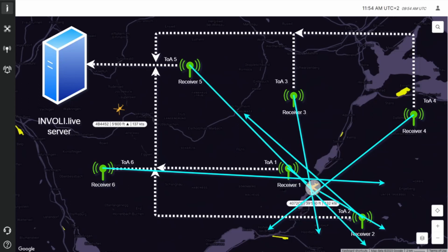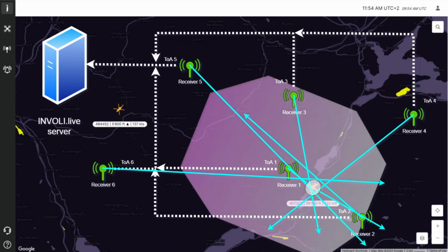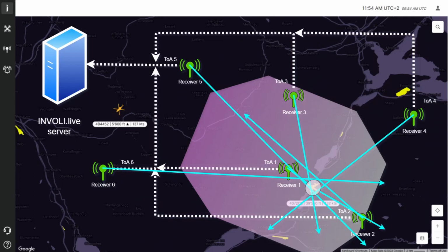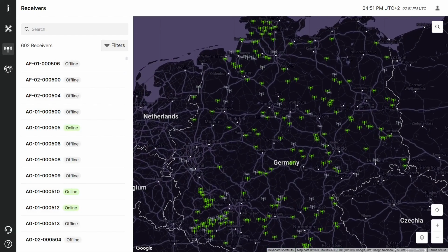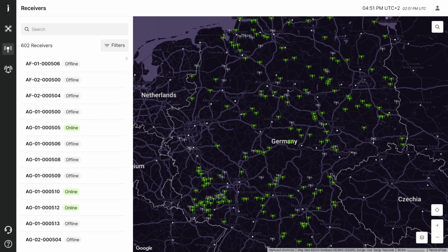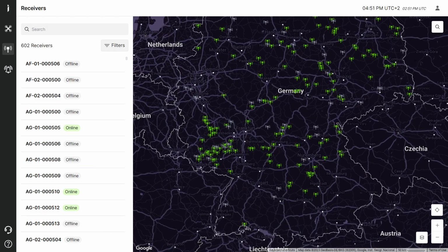An important factor in the precision of multilateration is the spatial distribution of the receivers. The receivers form an area inside which the location estimation is the most accurate. Going outside of it, the accuracy of position degrades quickly. Such processing is possible for any signal type: ADS-B, Mode S, Mode A/C. For the signals carrying the position, the validation of the reported data is the biggest advantage.